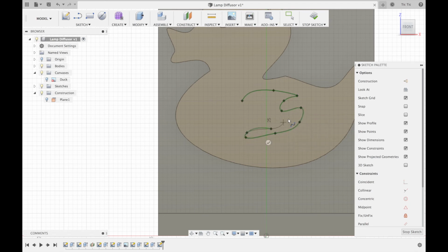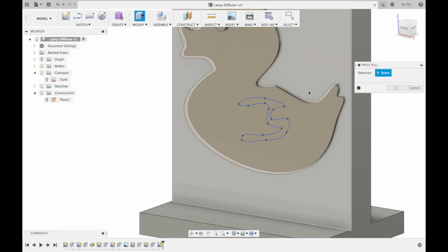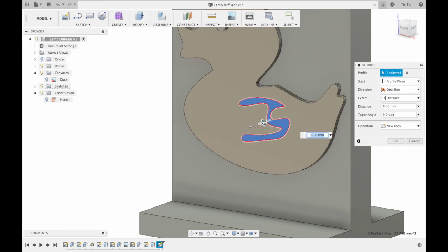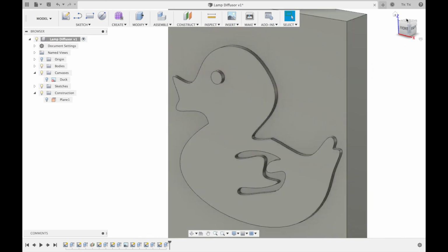And remember, I've got to create my wing such that it's actually, this is not a very good one. I usually spend a lot more time on this. Hit Stop Sketch, and I might want to push that in, Q, modify that in, maybe 1 millimeter. So you can see that I've got that sketch happening.